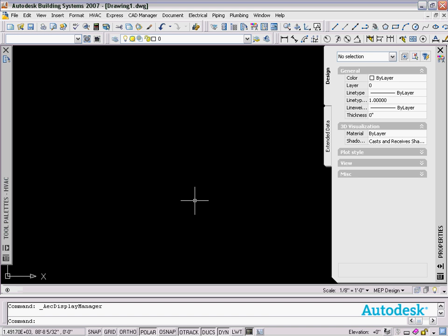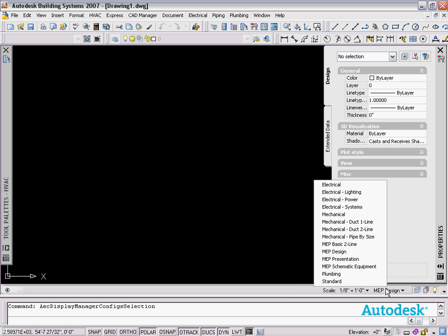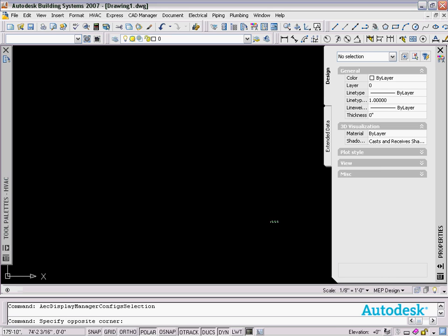In those situations, pretty much what you see is what you get, and their display is controlled mainly by the layer. With an object, there are multiple ways to display that object, and it's still the same object without making a layer change. Those types of settings are controlled by the Display Manager, the central location for making display changes within the ABS and ADT programs. The end result of those changes is usually controlled by setting a display configuration. We'll talk about that a little bit later, but let's first talk about the objects themselves and their representations.